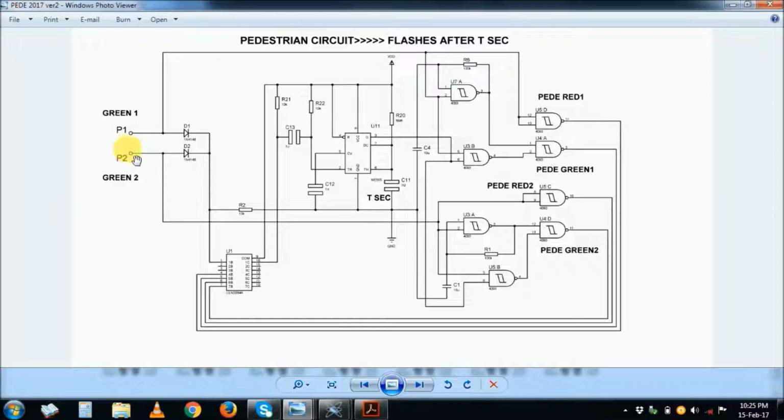So it is like a logic flip-flop, where you can say P1 and P1 bar. So this one is complementary. One is on, the other is off. Suppose P1 comes on, is a high, meaning this one is a low. So this high comes, goes through the diode to trigger that timer. So we have a high coming there and trigger that one, so the output here becomes high. So number 3 is high now.